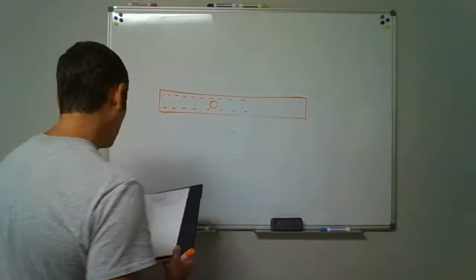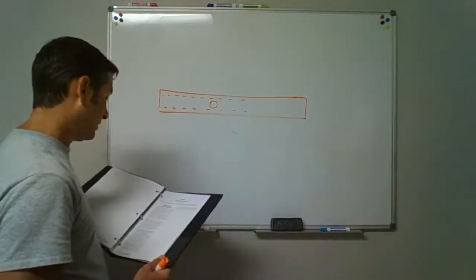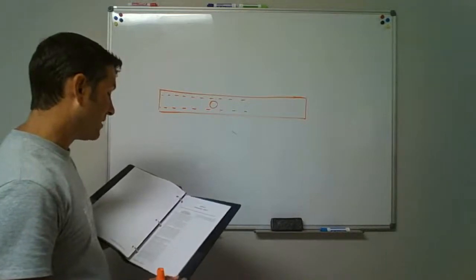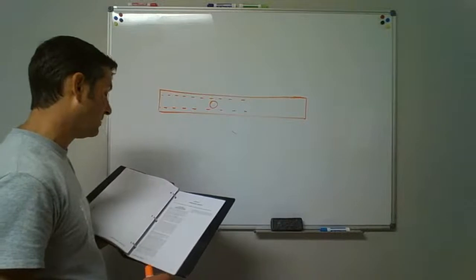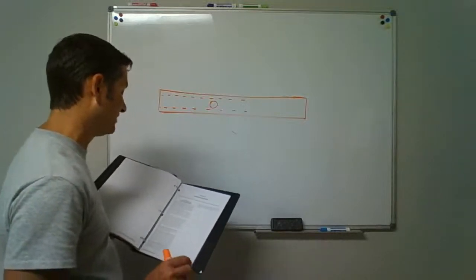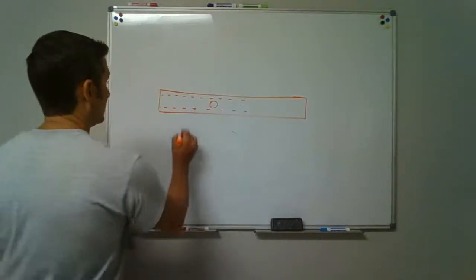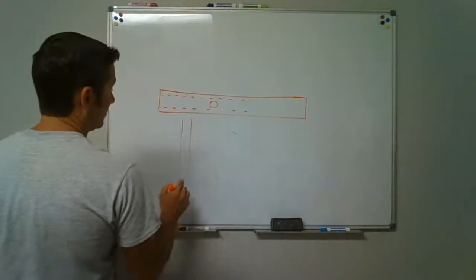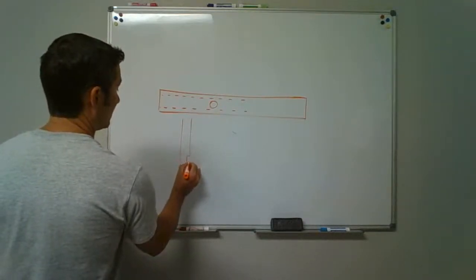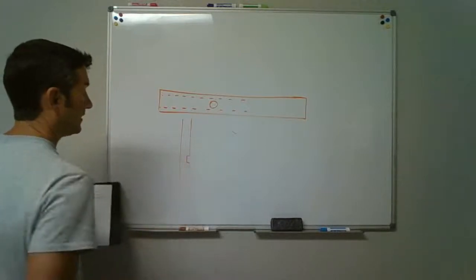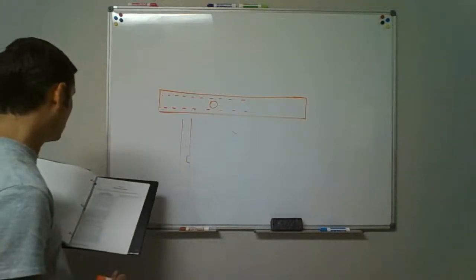Then it talks about stud cutting and notching. Exterior walls and bearing partitions, any wood stud is permitted to be cut or notched to a depth not exceeding 25%. So if you've got a stud which goes vertical, you can put a notch in it, but not more than 25% of the depth. Okay.